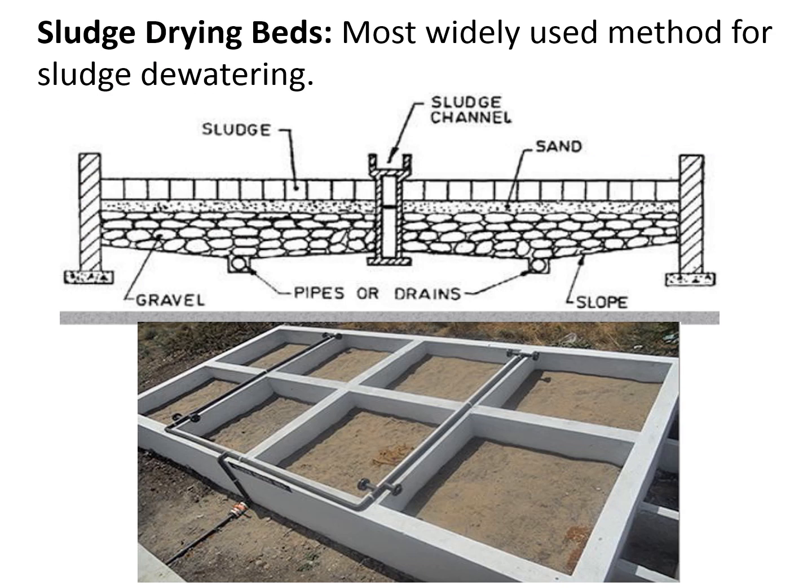And the last one: after digestion, the digested sludge is to be applied for further removal of moisture, and this is generally called sludge dewatering. The most widely used method in India is the sludge drying bed. They are simple beds consisting of sand and gravel. You just apply your digested sludge over that and dry it for 14 to 15 days.